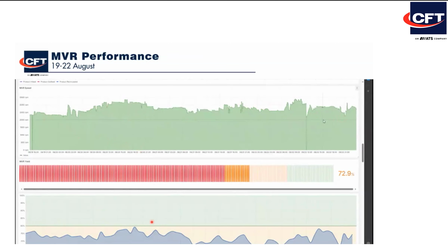We can also see the energetic efficiency of the compressor, which means the ratio between the energy delivered to the fluid, which is the vapor, and the energy absorbed by the electrical motor. Overall, the compressor had an efficiency of short of 73%.